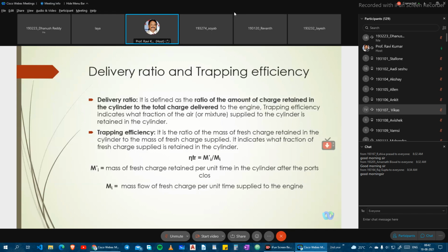And there is also a frictional factor, because we have moving parts. The piston is always moving from TDC to BDC, so we have some frictional losses. These problems happen inside the combustion chamber and decrease the efficiency of the engine.